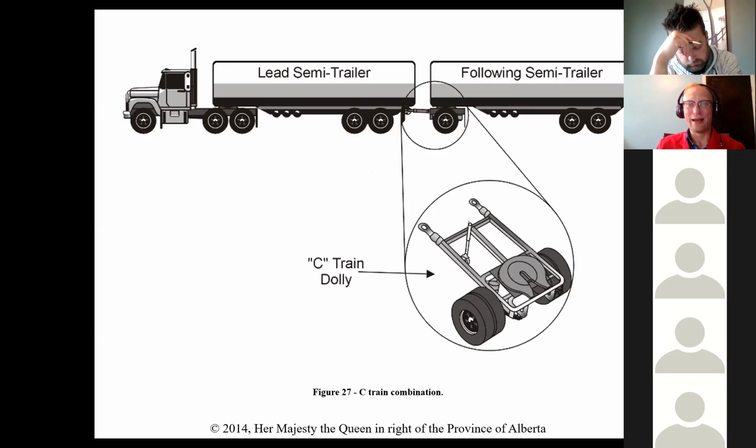It's messed up. Yeah. That's the reason why axles aren't solid tubes of steel, because you'd never be able to drive down the road with that much unsprung weight on there. They'd weigh so much. They're hollow tubes for that reason. So steel is quite heavy. When I was at Maximum, when we did our tank inspections on our fiberglass tanks, we actually had to take the bolster plate, like the fifth wheel plate, the whole thing, right off so that they could look for cracks underneath.